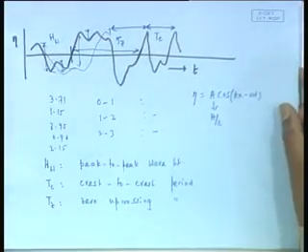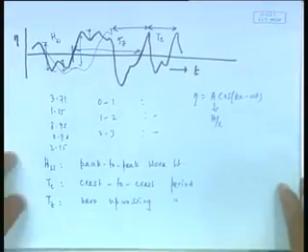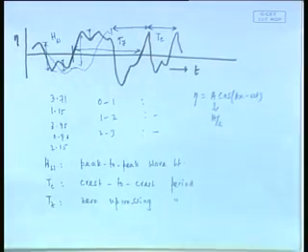For period, it is crest to crest or zero upcrossing. Length is also the same thing, height is peak to peak. Now, let us look at the height. The height is the most important one, because I will come back to this diagram again, because everybody knows that the higher the wave, the more severe it is. We always talk in loose terms that waves are so high, 30 meter high, 20 meter high. Height is a measure of severity.